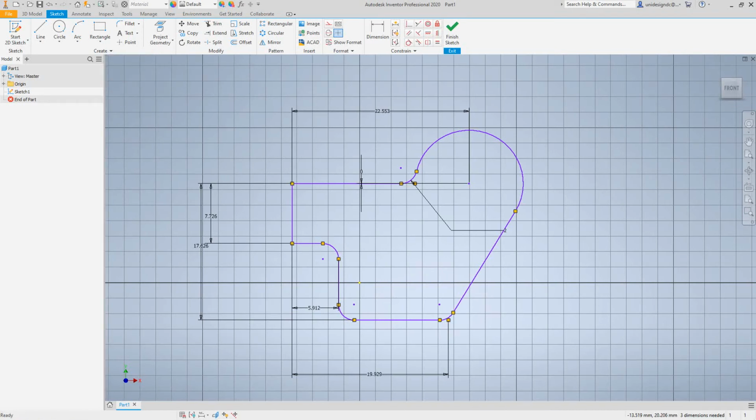So that's done. Now we want to adjust the size of this thing, so we want to modify it. To adjust the size and keep everything locked in proportion, we need to do this, because I want to make this bigger. So I want to lock this and constrain that, so the whole model is fully constrained.